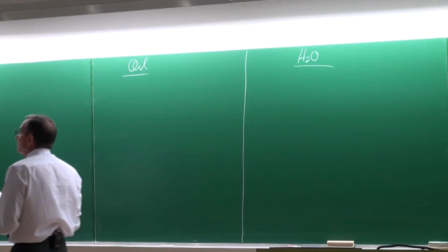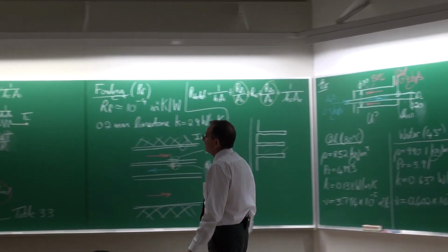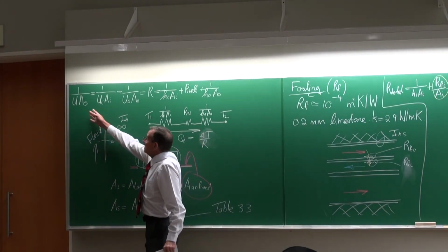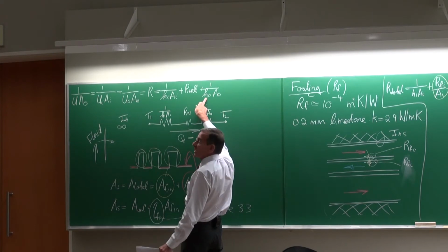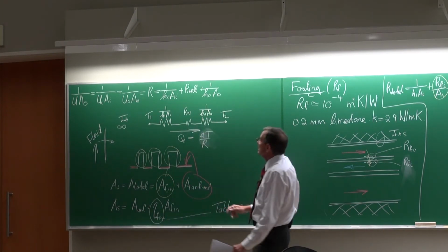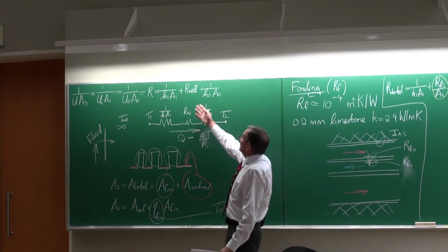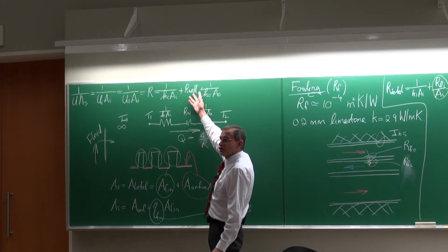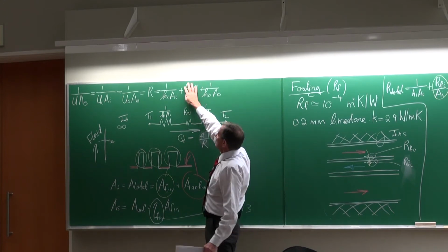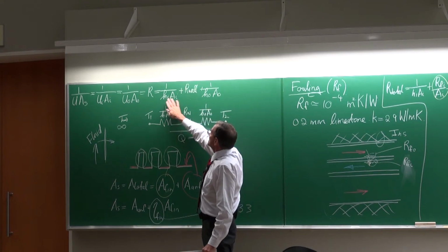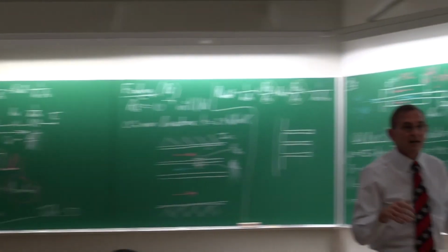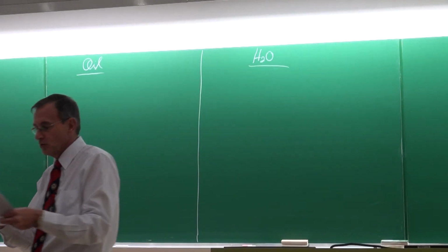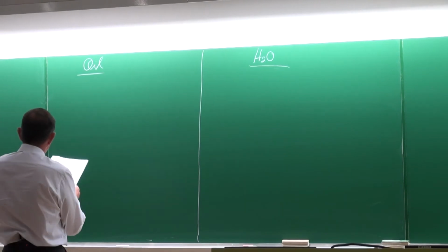So in terms of the overall heat transfer coefficient, if we just look back here, we can see that we need the heat transfer coefficients on the inside and the outside, and we need the areas on the inside and the outside. They've not given us any information on the wall except to say it is a thin wall, so we will get to that a little bit later. But I think the focus at this stage should be quite clear: getting to two heat transfer coefficients. That is normally the big challenge when you work with heat exchangers. You need to get those two values.